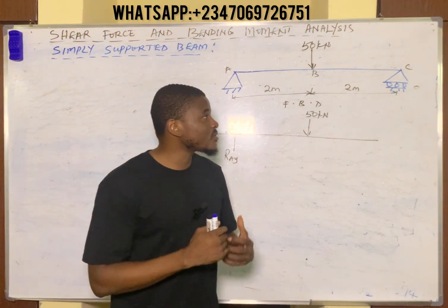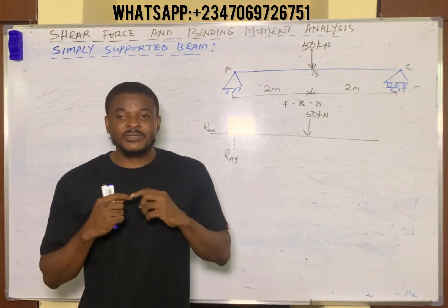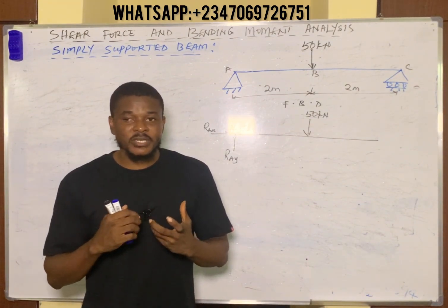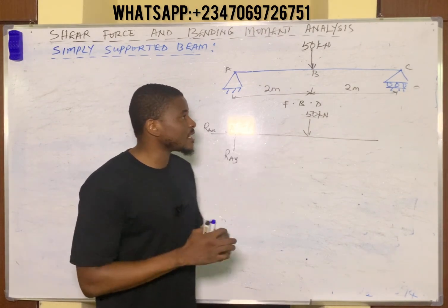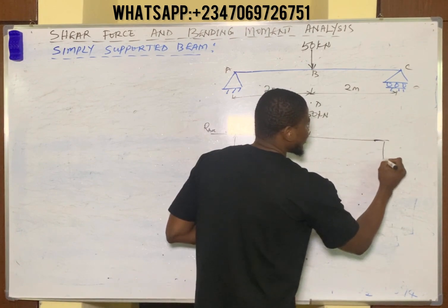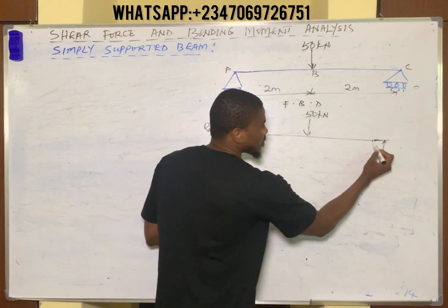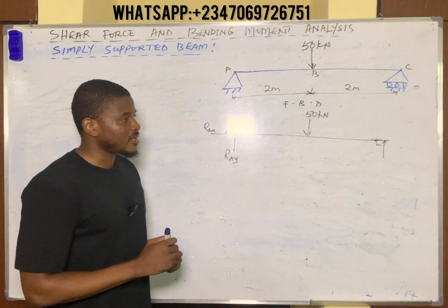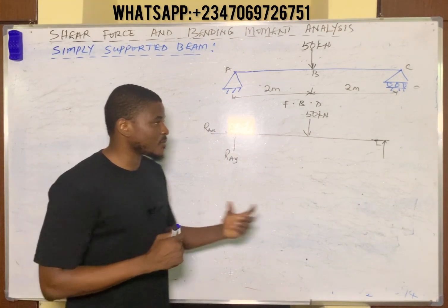Okay, so every roller support must always have one reaction which is perpendicular or at 90 degrees to the point where it is occurring. So since this beam is horizontal, this reaction here will simply be a vertical reaction, because it makes an angle of 90 degrees with the surface where it is acting.